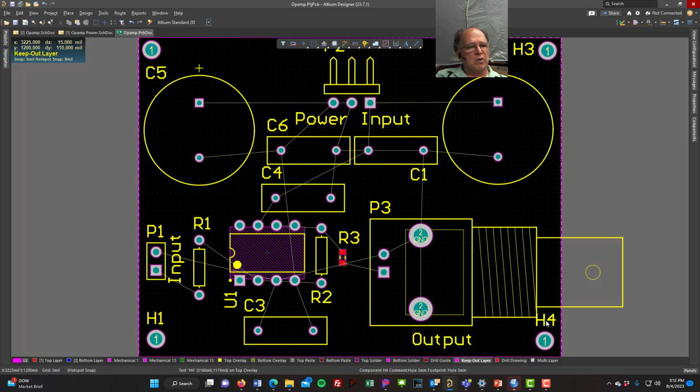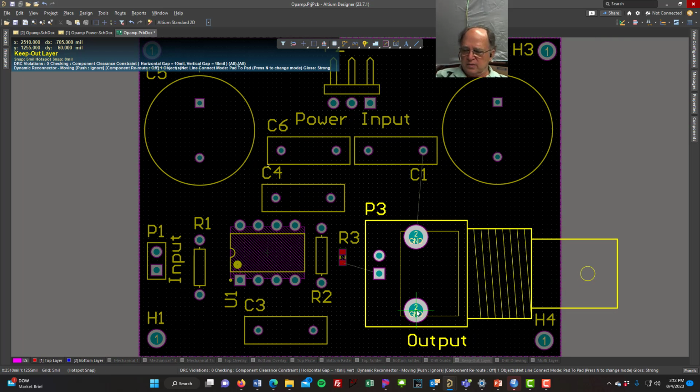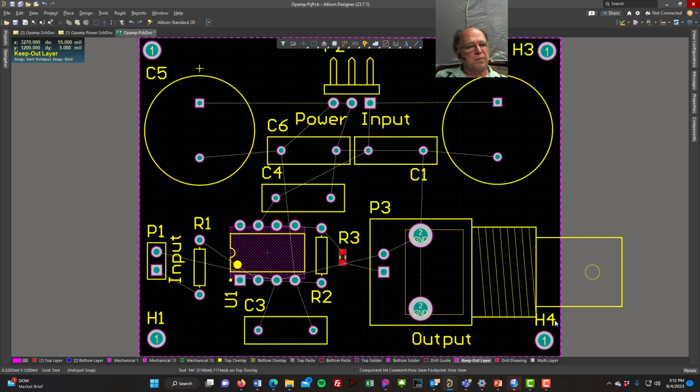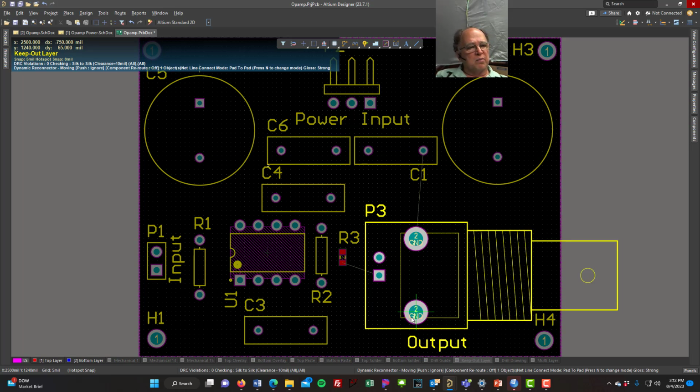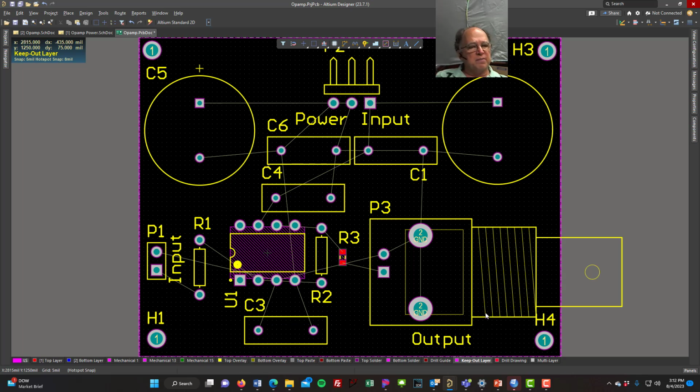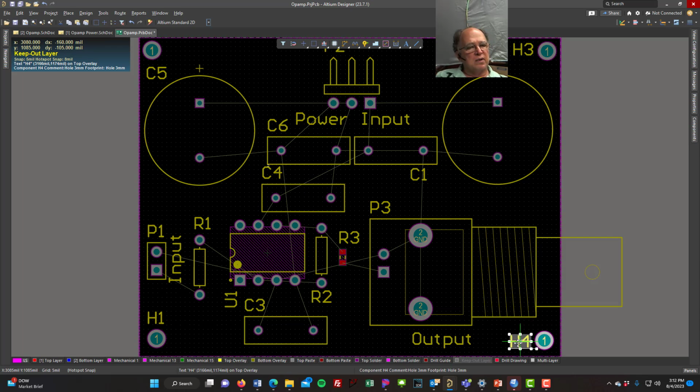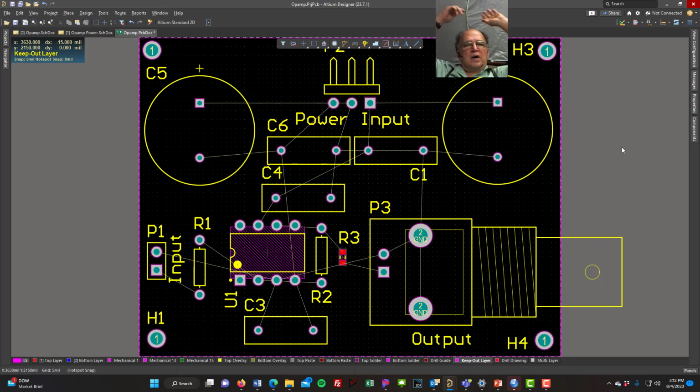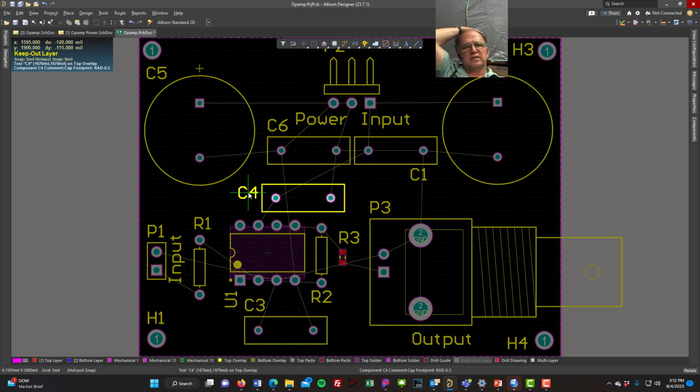I want everybody to go ahead with their design now and see if they can update their design, move their parts to the PCB. I'm trying to grab that H4. It doesn't want me to. There we go. Update your PCB, move your parts around, play with the rooms, see how you can have a room and get rid of a room. You can move your designators around.